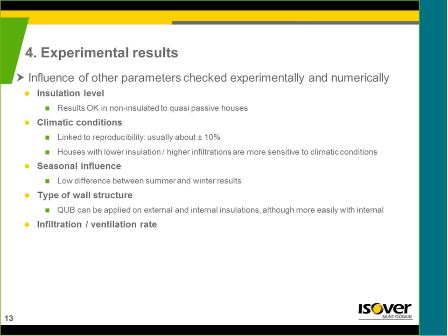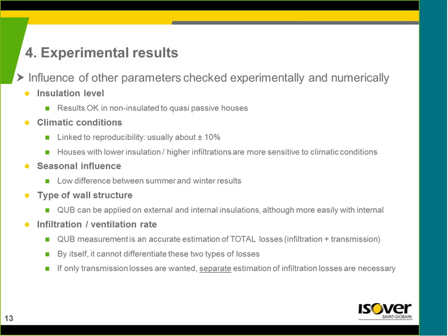It would be difficult to explain all the differences in such a short presentation. I will just say that with internal insulation, we can be faster, more accurate, etc. Now, a short point about infiltration and ventilation rate. What we measure is the heat loss coefficient, an estimation of total losses, infiltration and transmission. By itself, the method cannot differentiate these two aspects.